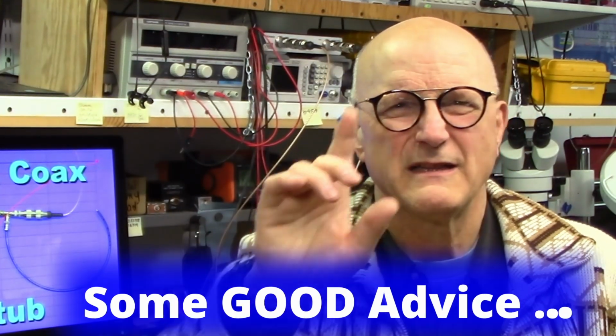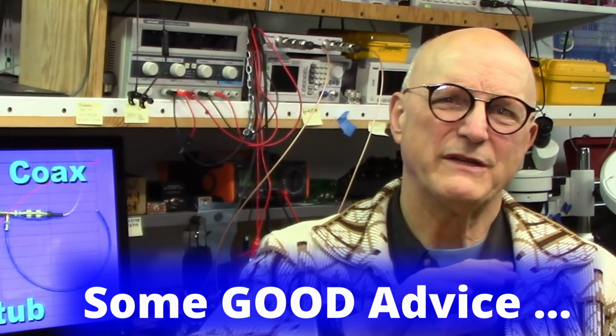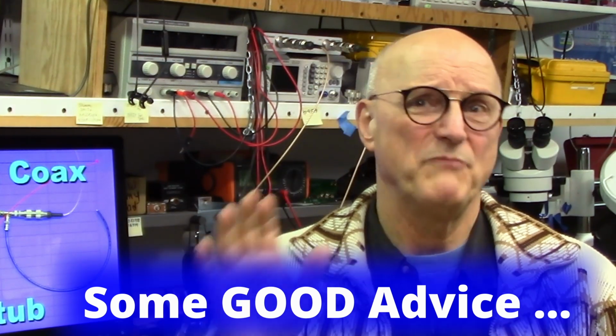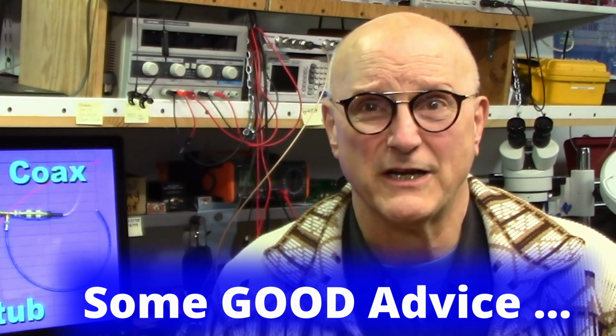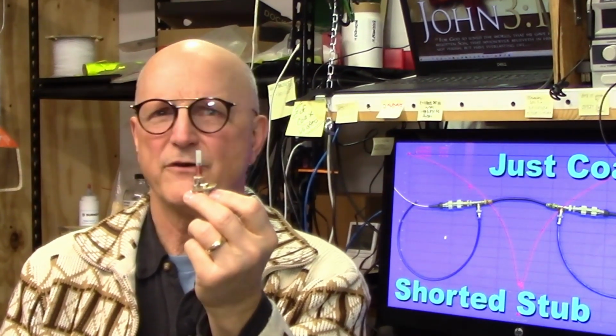But before I begin, let me give you one piece of very important advice. When you're doing this, be sure to build in enough variability into your design to accommodate variances in velocity factor, measurement lengths, connector and adapter velocity factor differences, and all of this stuff. Because there's a lot of, well, let's face it, RF magic going on here. So let's start with way one. With way one, we start with an inductor that we want to use and calculate the cable lengths we need to create to use it. My variable inductor varies from 200 to 400 nanohenries. So I'm going to design around 300 nanohenries, halfway through its capabilities.